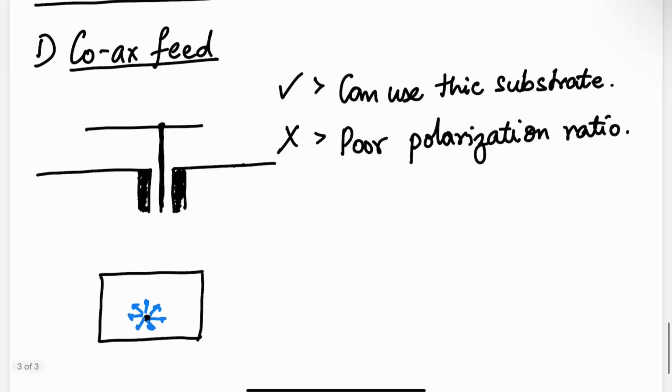So these fields can excite this mode, but since they are radially outward, they can also to some extent excite even this mode. Usually that mode would resonate at a different frequency, but frequencies are not completely confined, right? So you can have some of that tail of your bandwidth from this mode creeping into your actual mode of interest. So you can get a higher crossport